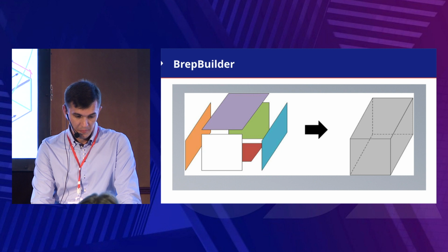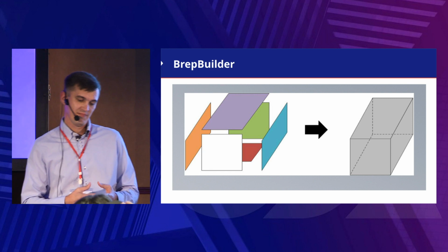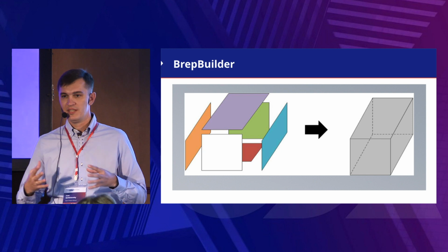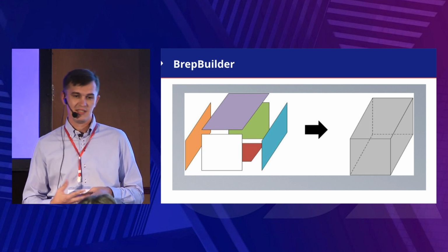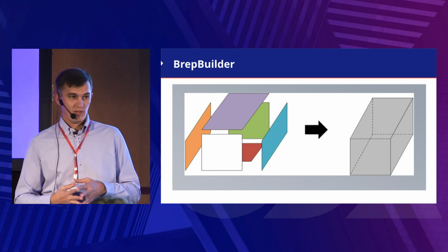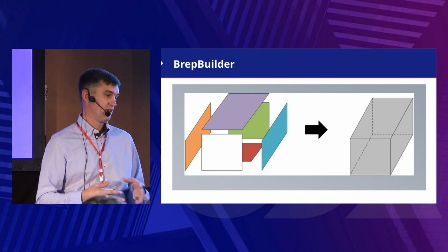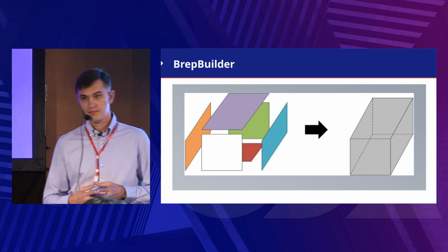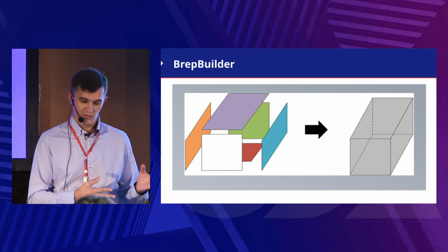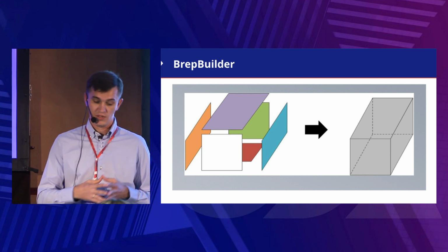So for the BIM SDK, BREP builder is also very important because many of our elements contain BREP data inside, and our BREP data is different if you compare it with ACIS, for example, or Parasolid. So we implemented a BREP builder interface. It's a helper for converting some customer BREP representation, or for example ACIS BREP representation, to our own BREP representation.